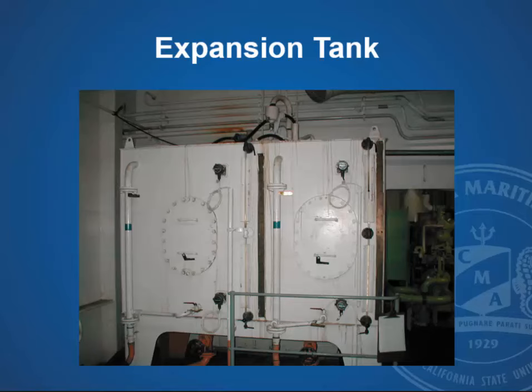The last subject that we'll talk on this is cracked liners and cracked covers. If you were ever to walk up to one of these expansion tanks and you're looking into the sight glass and you see rapid bubbling like it's boiling, walk over to the vent and take a whiff of the vapor coming out of the vent. If you start hacking and coughing, that's exhaust gas. And that exhaust gas is getting into the cooling water system through a cracked liner or a cracked cover.